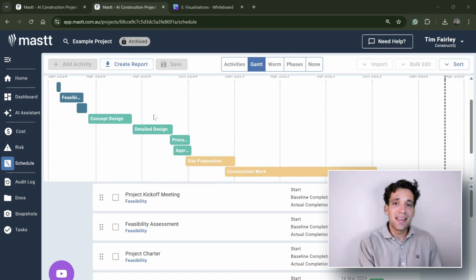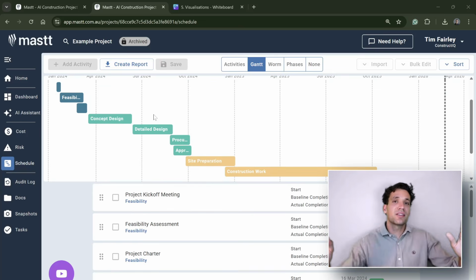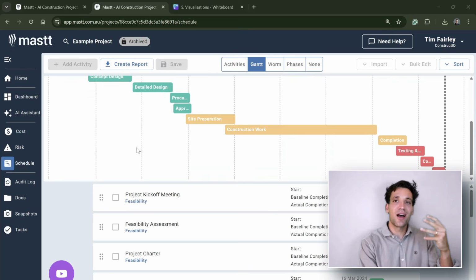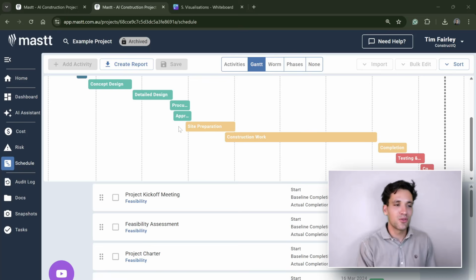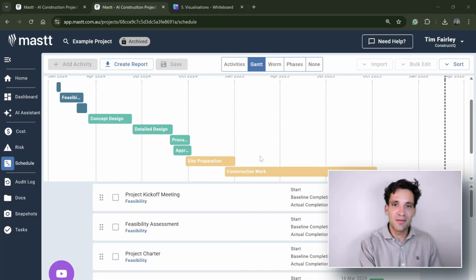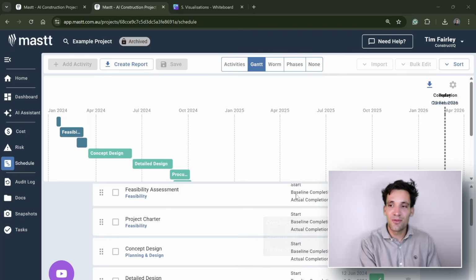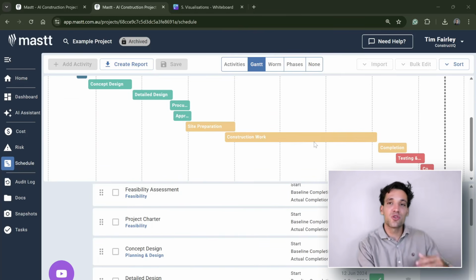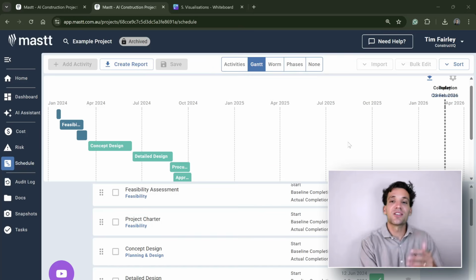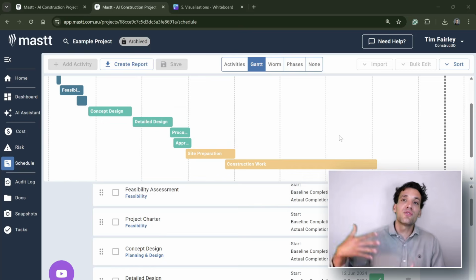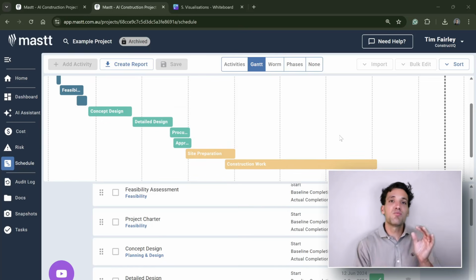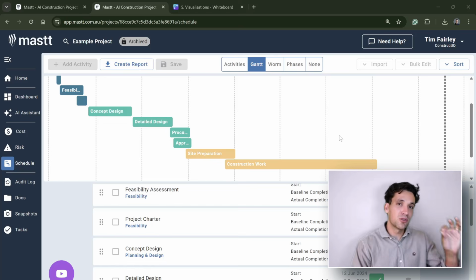Now, this doesn't need to be any insanely complicated 2,000 line P6 schedule where you have 100 different activity dependencies for every task and you have all these tasks with different varying degrees of float, and it takes 4 weeks to make any minor schedule update. Something really simple like an overall Gantt chart with the key stages of the project mapped into the key phases with indicative durations and what your original budget was built on. Say it was a 12-month project, just mapping these out. Then once a week, tracking how these are all progressing. Because if you can forecast out the duration of the project, you can much more accurately forecast your preliminary costs.